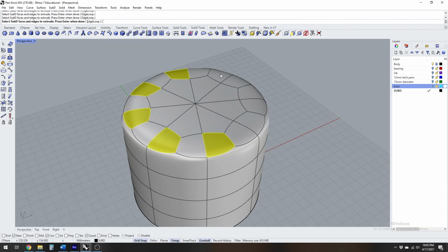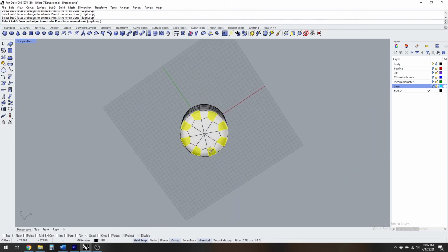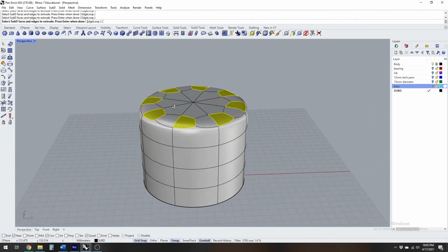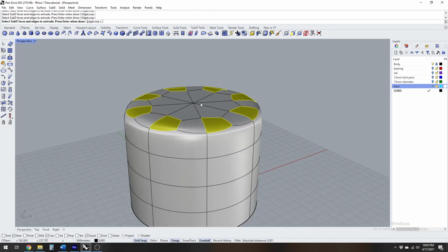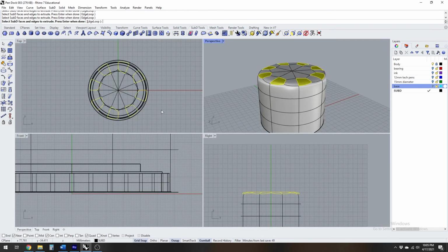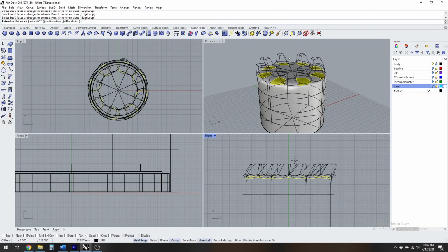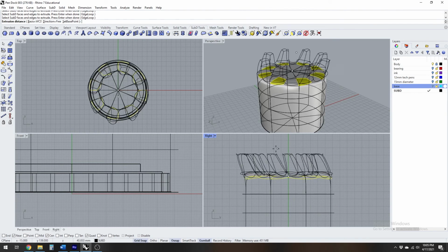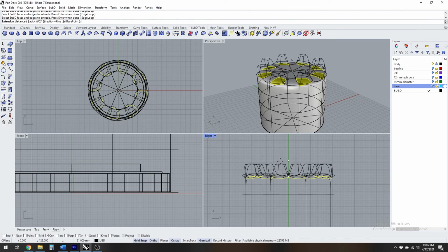And that means that we are never going to fillet anything ever again on a SubD surface. Well, we might do a little blending, but for the most part, you can see that I can select individual faces, and then via our extrusion command, I can literally insert more faces as an extrusion.